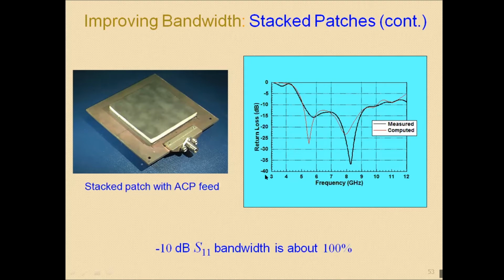Minus 30 dB, 35 dB, 36 dB, and all is 99.999%. It is transmitted. Only very little reflection is happening, right? If you achieve a minus 14 dB level, that would be better. So here, the bandwidth you see, when you extend the line to the x-axis, it would be this point: 5.2 gigahertz to approximately 9 gigahertz is the bandwidth of this antenna, right? This stacked patch antenna has its bandwidth as 5.2 gigahertz to 9 gigahertz, a very wide bandwidth.